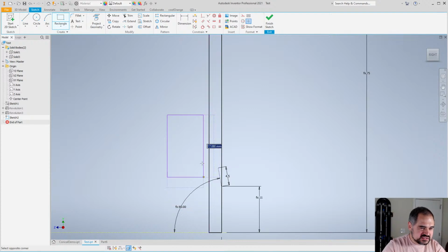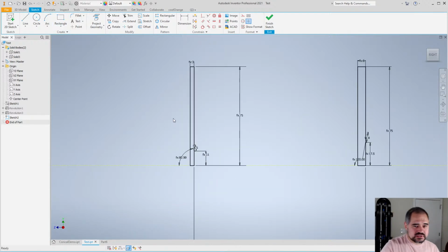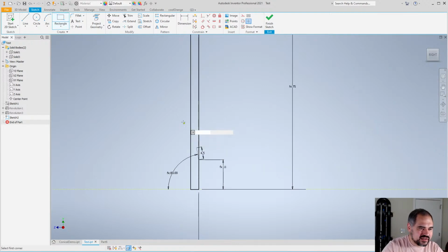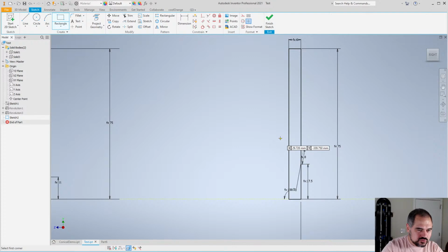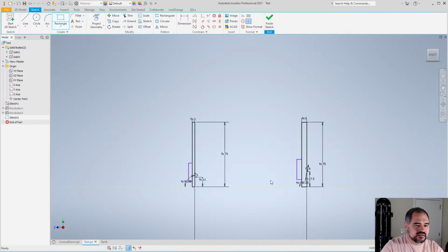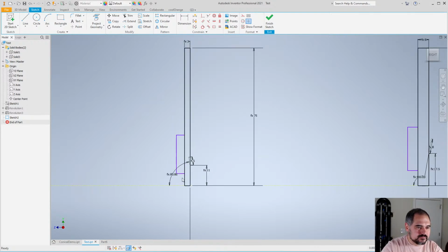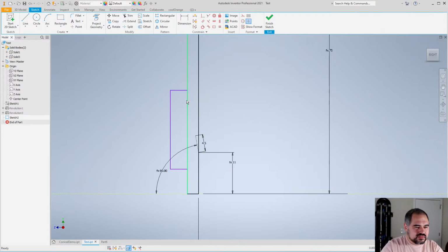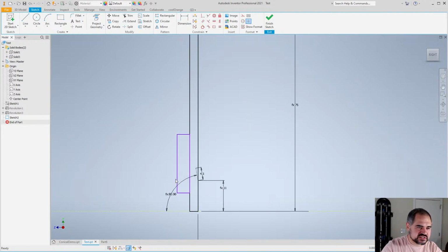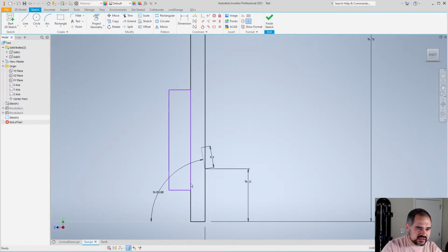One more thing we're going to do in this step is create the risers. Now, some of these tone holes aren't going to need risers. They're short enough. But once again, I find it better to model the riser, and then if it doesn't need it, the steps we'll do later automatically get rid of it, rather than thinking you don't need a riser and then having to go through and manually change everything. So this is just another rectangle on the outside of the tone hole.